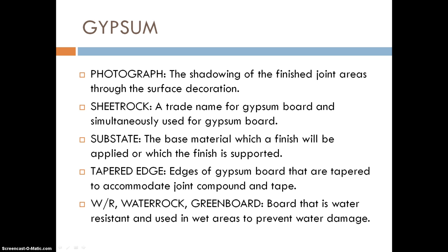Tapered edge, edges of the gypsum board that are tapered to accommodate joint compound and tape. Water rock, a green board that is water resistant and is used in wet areas to prevent water damage. And that would be like the kitchen and the bathroom.